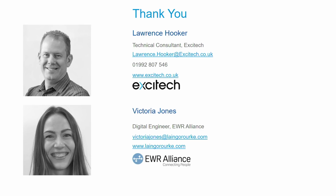Hi, thank you. So I saw that you are using a lot of custom nodes. Were you forced, let's say, to use Python at any point? No, no. Everything in my presentation is using standard Dynamo nodes. I haven't used any custom nodes at all. There are instances where you might need to use Python, but as a general rule for myself, if I do use custom nodes, I tend to depackage them. Because the problem is, if you share the Dynamo script with someone else that hasn't got the package, it causes havoc. Yeah. Quite right, yeah.